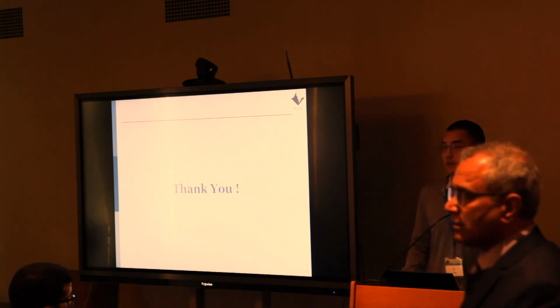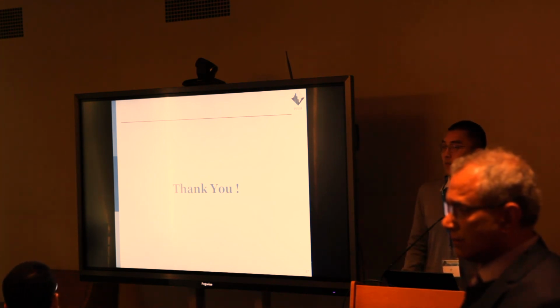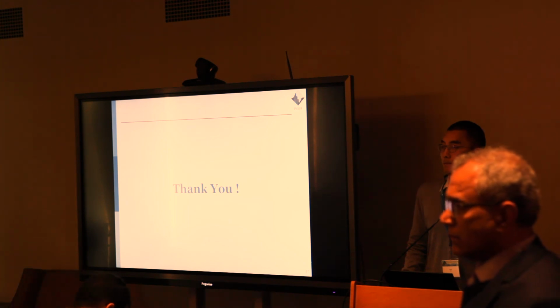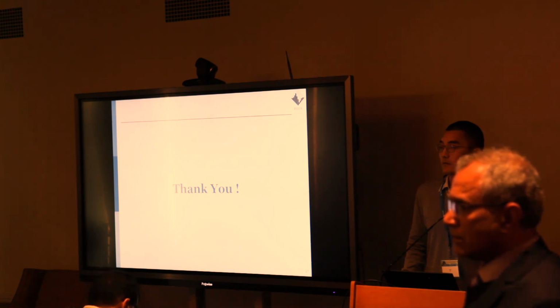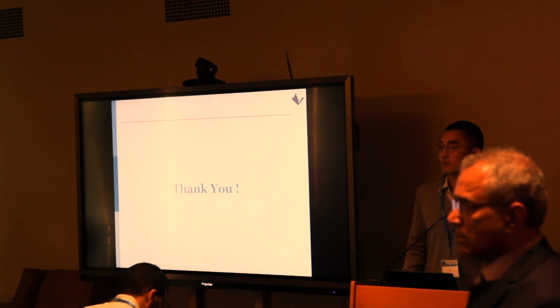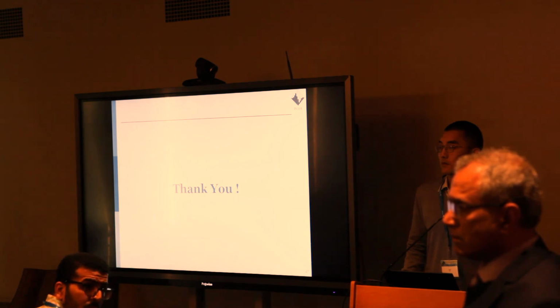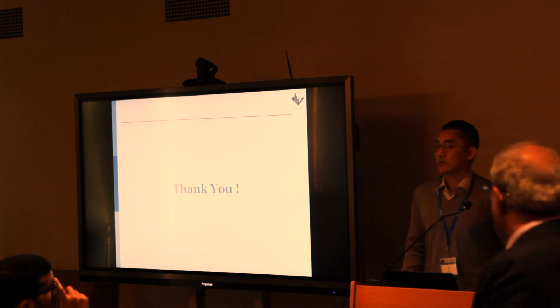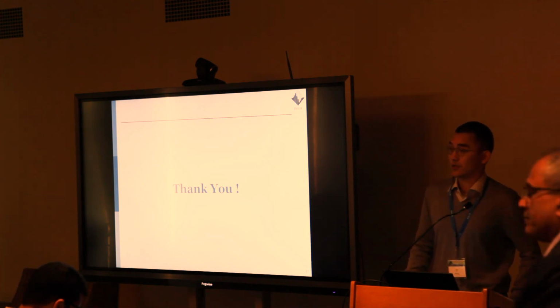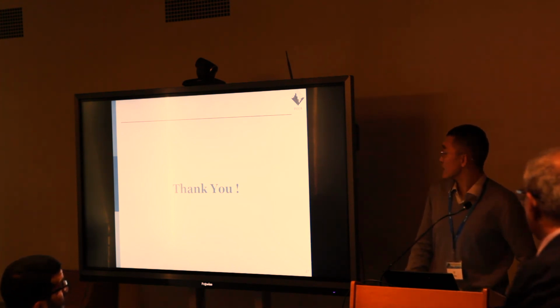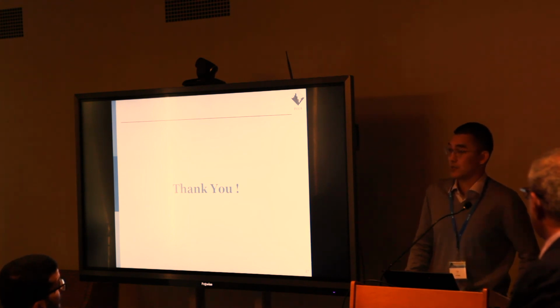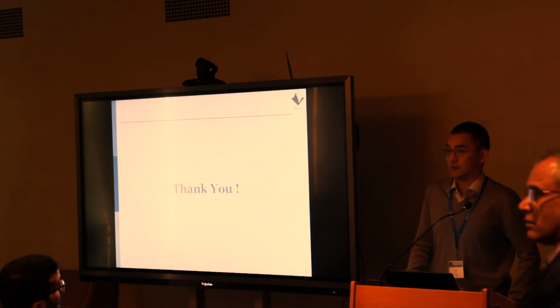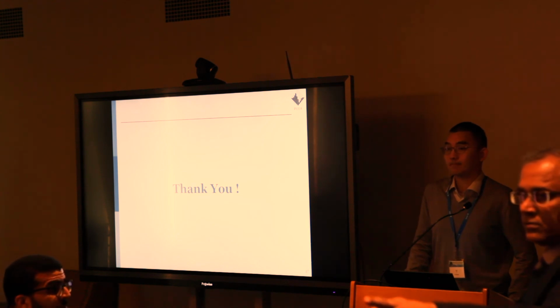Okay. And did you actually model the entire backbone curve of the behavior of the shear key, including the fracture or the failure of the shear key, or did you have it just as elastic, completely plastic? So you mean in the transverse or in the longitudinal? In the transverse. In the transverse, the material behavior we use is the elastic, perfectly plastic material.